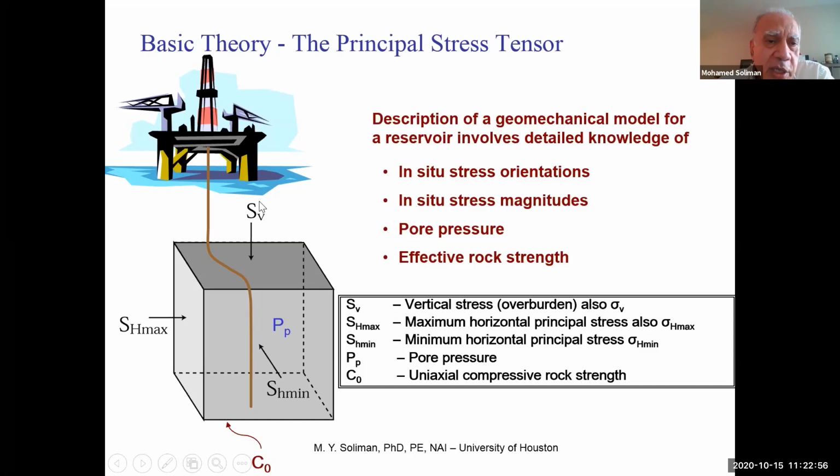But you break the stresses into three perpendicular stresses, a vertical and two horizontal. I will call that SV, my total vertical stress. The two horizontal stresses, one usually is bigger than the other, so I'm going to call them SH max and SH min. And then your fluid will have a pressure. There is a pore pressure inside the pores, because the rock is not completely solid. So there are pores inside, and this will have pore pressure. It's important to think about that.